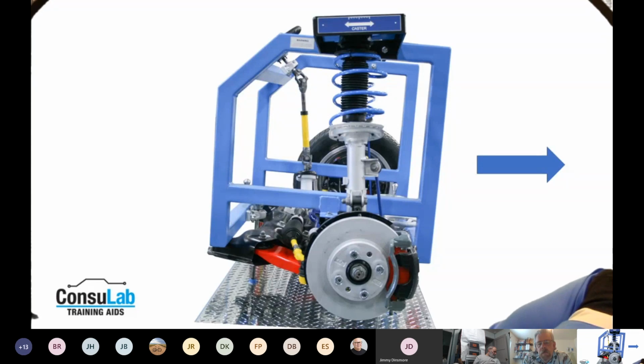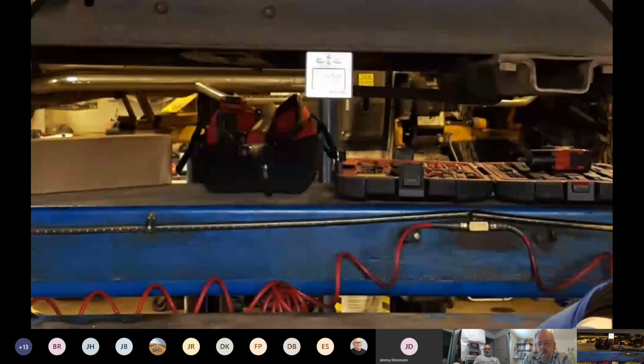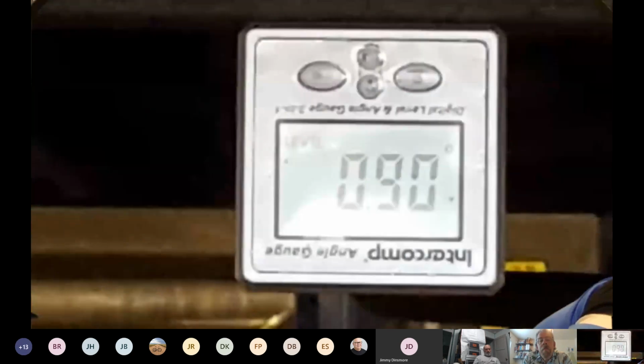So there are many manufacturers, and especially in pickup trucks, where they'll actually ask you to measure the frame angle. So we compensate for these tilts and actually are going to measure the frame angle. And a lot of aligners now actually have a spot where you enter that into the specs. So you get a magnetic degree indicator and stick it to the frame or to a level part of the vehicle and actually measure the angle and put that into your specifications.